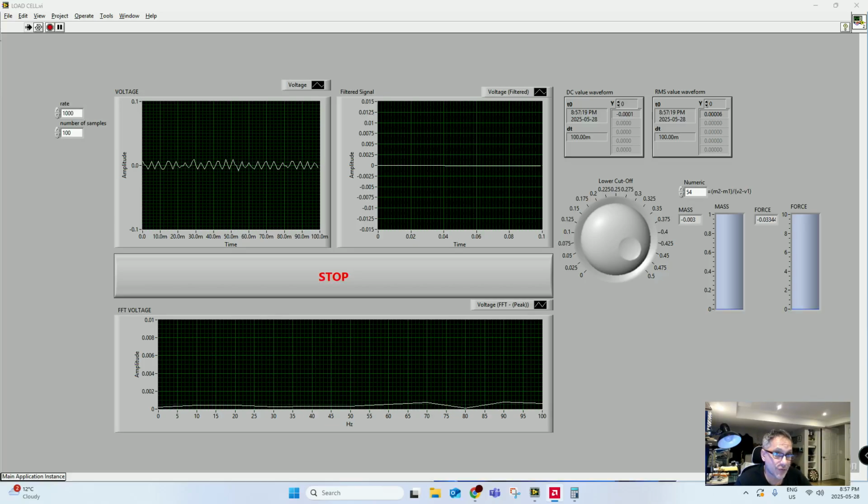Today we're going to talk about how to capture the load cell signals by using the DY510 connected with the National Instruments NI 6009. Alright, what you're looking at right now is the signal captured directly from the load cell.